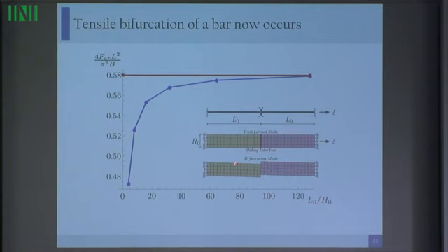The very last test we did was done numerically because we weren't able to solve it analytically, so we have these two Neo-Hookean layers separated by a sliding interface. We pull them in tension and we see that we find bifurcation, and actually the solution converges towards the solution of the two elastic rods when these layers become thinner and stiffer, of course. So at this stage we believe that the correct interface condition for sliding is that with alpha equal 1.